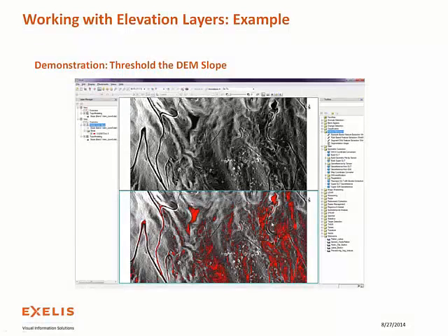Okay, so this here is the slope map that I constrained to just look at only the pixels that are less than 5-degree slope. So this is the slope map up here, and the red is everything less than 5 degrees. And then you see that we have a lot of noise here of these smaller areas that are not suitable based on our size. And I used the sieve tool to sieve through those and say if it's not at least 1,000 square meters, just delete it, remove it.